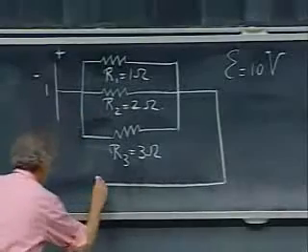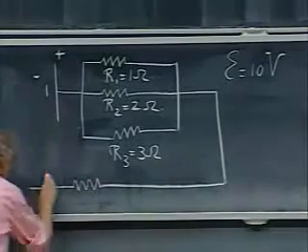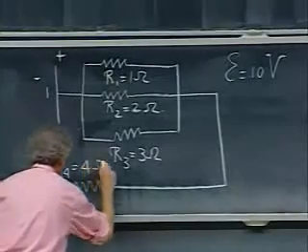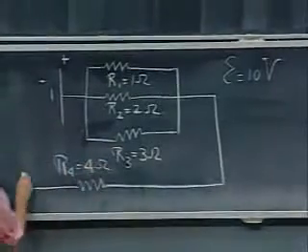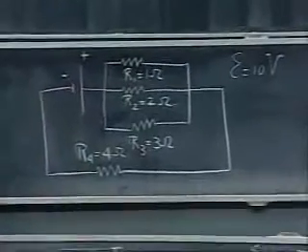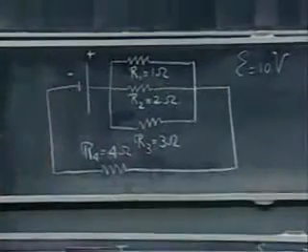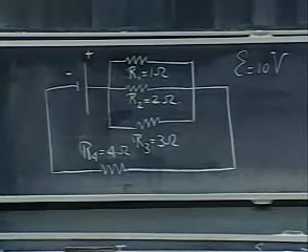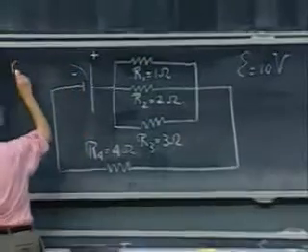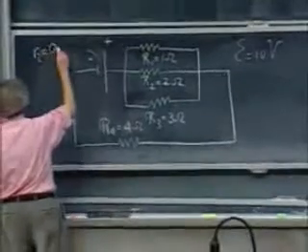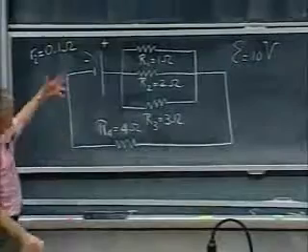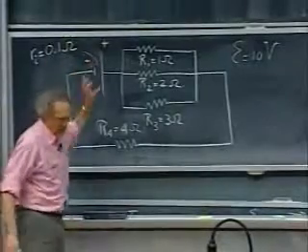And here I have a resistor R4, which is 4 ohms. And I close the loop and go back to my battery. Just to make it a little bit more interesting, I will introduce into this battery an internal resistance which is very small, which is 0.1 ohms. You can't remove it. It's intrinsic into that battery.